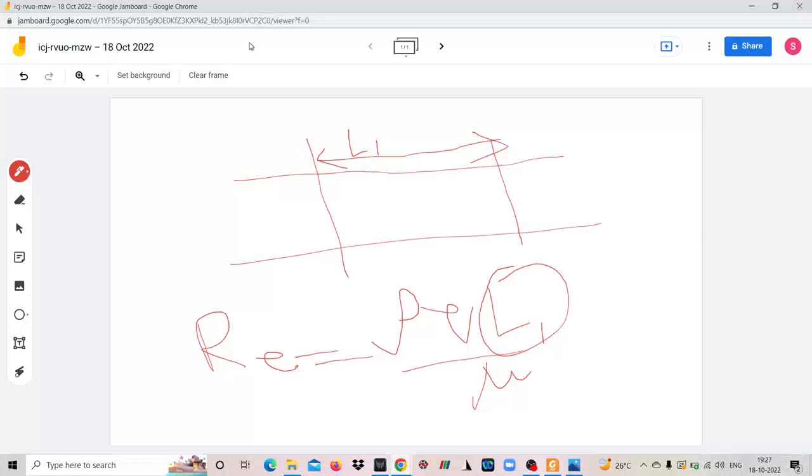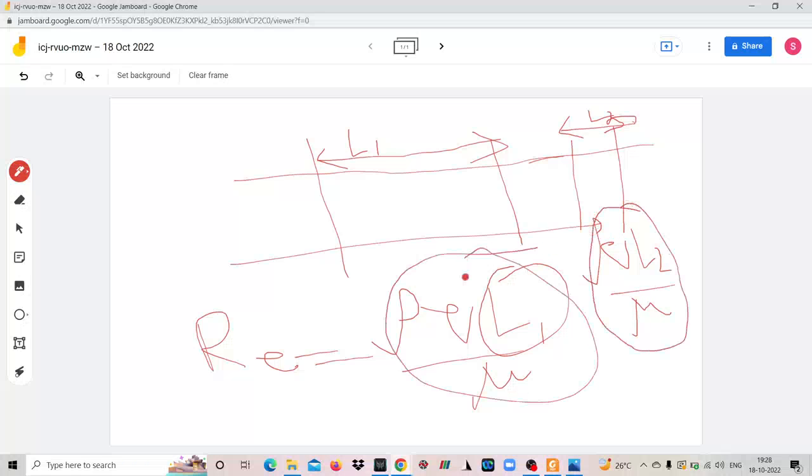But suppose you want to study only another stretch, a short stretch whose length is L2. For that the Reynolds number is rho v L2 by mu. So this Reynolds number will be smaller than that Reynolds number, right? If you consider the entire length of the pipe, say it is rho V L by mu, that will be the highest Reynolds number. So see, Reynolds number is also changing. But for a fully developed pipe flow, if it is a horizontal pipe of uniform cross section everywhere, then the Reynolds number is fixed, rho V D by mu. So that is more realistic, right?